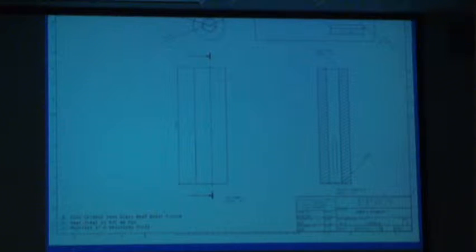A number of things that you'll notice right away. There's a border around this print. You've got numbers along the sides and letters along the top and bottom. Those are very important when you go to communicate with someone who's going to manufacture your part. A lot of times they'll be somewhere other than you are. And if they want to ask you a question about this length dimension right here, they'll tell you it's at F4, and that'll tell you where on the part you're looking. That doesn't seem like a big deal on a part this simple, but I promise you, you've got 200 dimensions. It's very difficult to communicate about dimensions over the phone or with someone who's not in the room with you. So it really does help a lot.